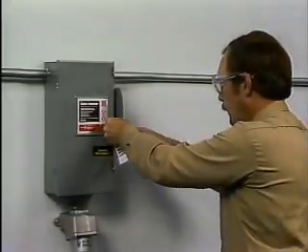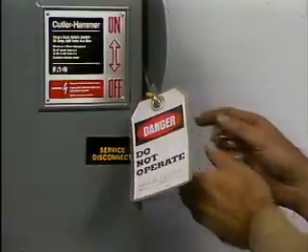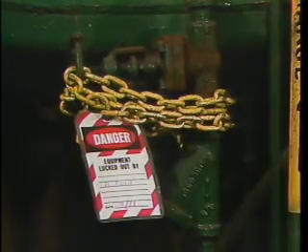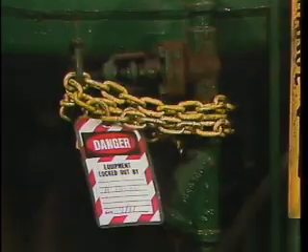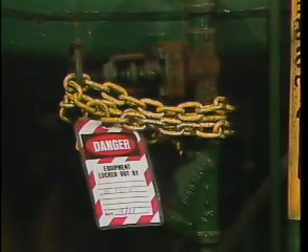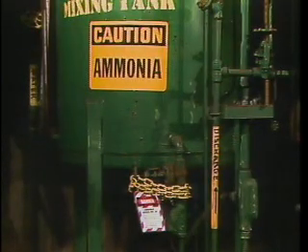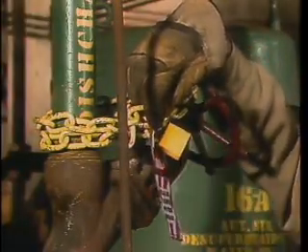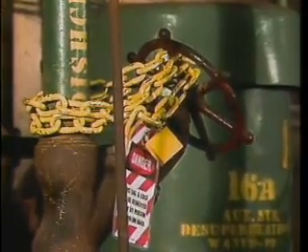A lockout and tagout procedure sets requirements on the types of locks and other energy isolating devices that can be used. For instance, all isolating devices, such as this chain that's used to hold a valve in the closed position, must be authorized for energy isolation. In addition, they must be capable of withstanding the environment they're used in. When locks are used, they must be substantial. That is, they must be strong enough so that they can't be opened without the key unless excessive force or unusual procedures are used.